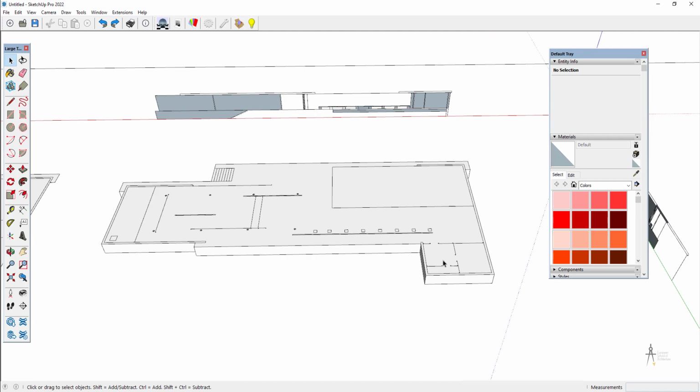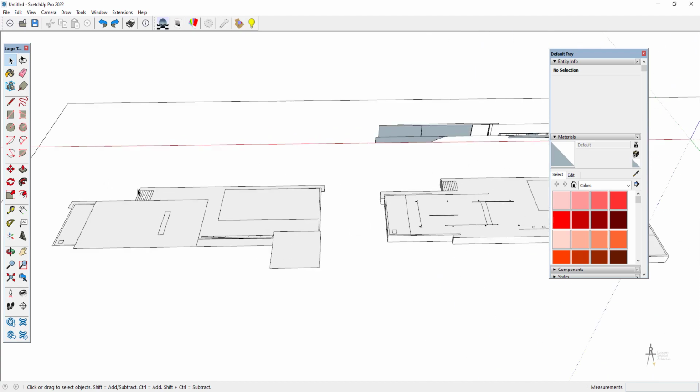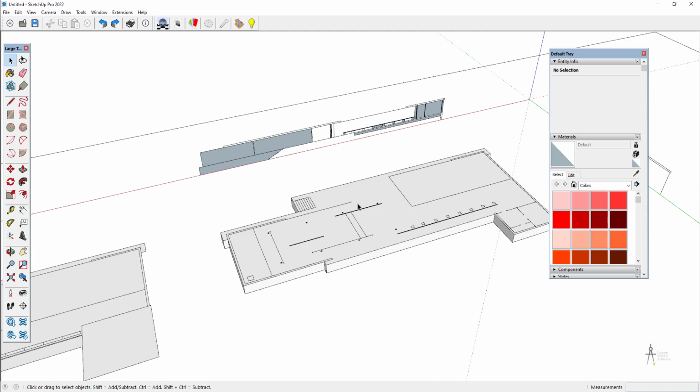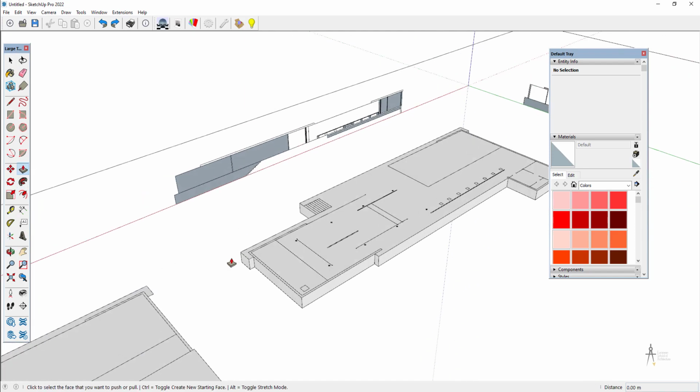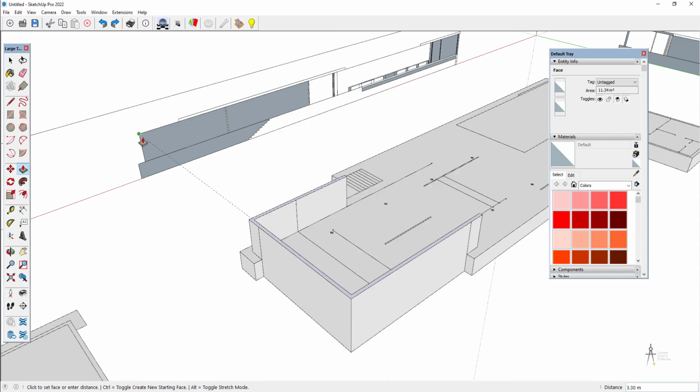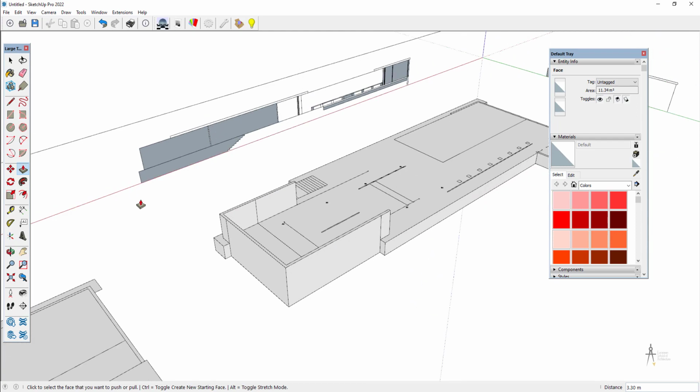Remember that we have two faces, and we have to make sure that when we extrude, all the faces look up. Remember you can flip your face if this happens. So first extrude, push and pull, we find this wall and a reference point here. Remember you can lock or fix the direction with the arrow.